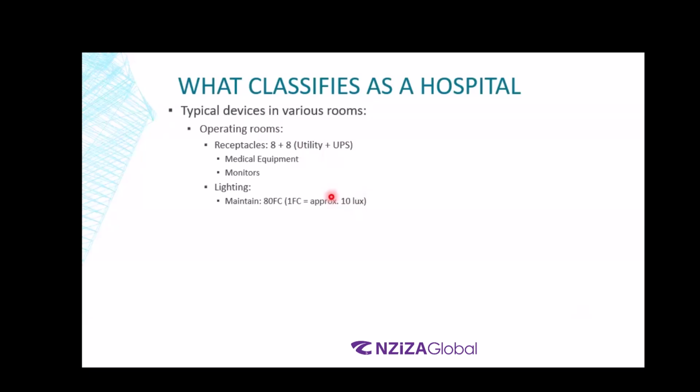This is a luminaire, also called lighting fixture, or sometimes only called light. Someone will even call them lamp because there used to be incandescent lamp, just one lamp in a given light fixture. So for a given hospital, what is expected is that the lux level needs to be somewhere around 800 lux. For an operating room, the recommended lux level is 800 lux.